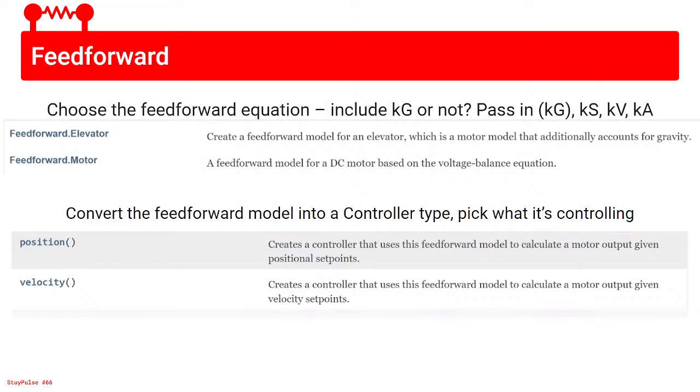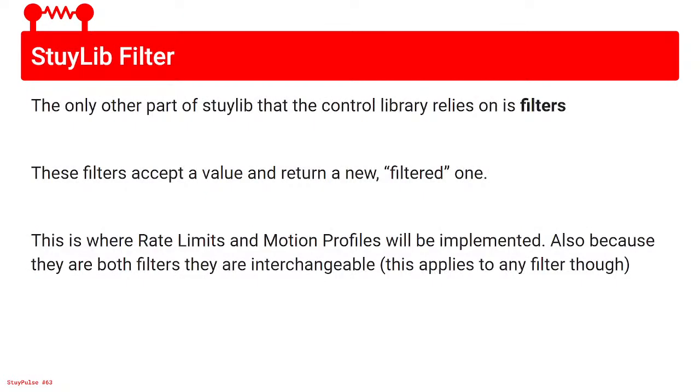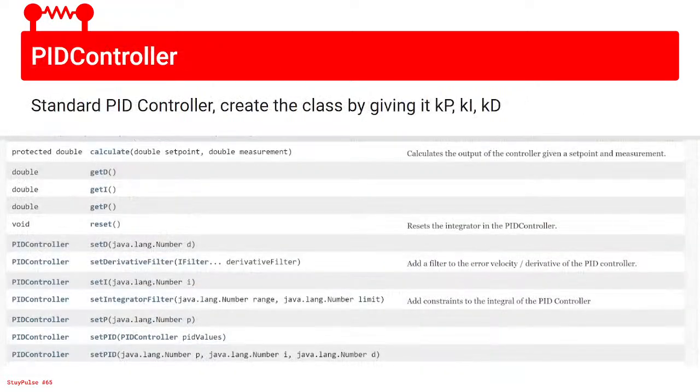Oh, yeah. Never used it, but I've seen instead of PID controllers, PIDF controllers. Mm-hmm. That just tries to contain all of the constants into one. Yeah, PIDF controller is a little old. The F is of course feed forward, but there's only one number for feed forward, which is not as accurate as having KS, KV, and KA. So KF would be analogous to KV, but then once you add on those 2 other terms, you get a better response. Does that make sense?